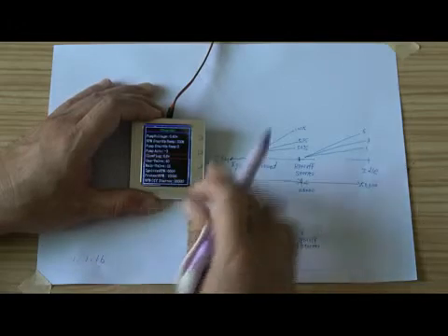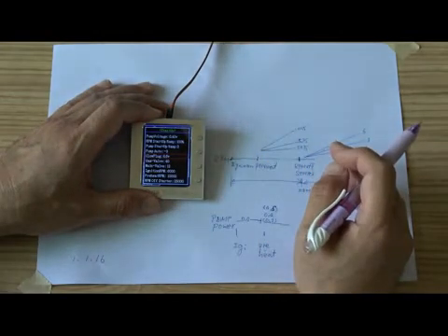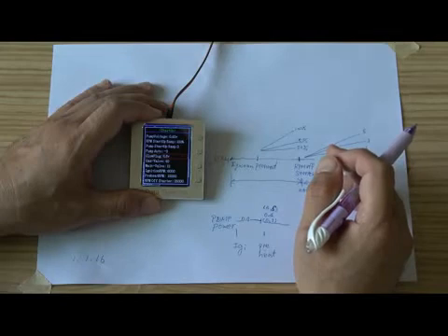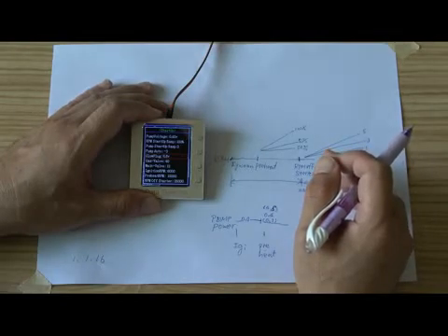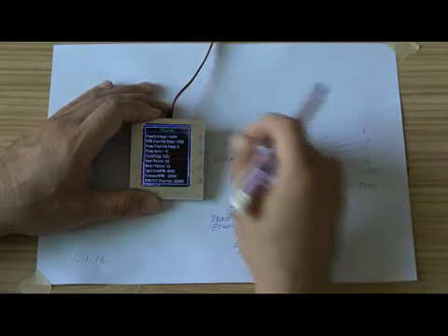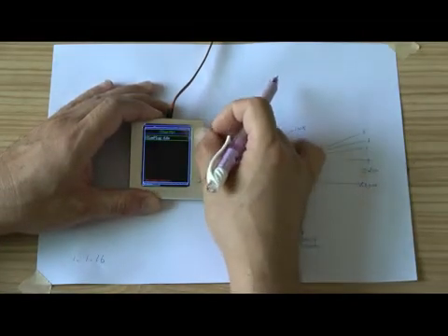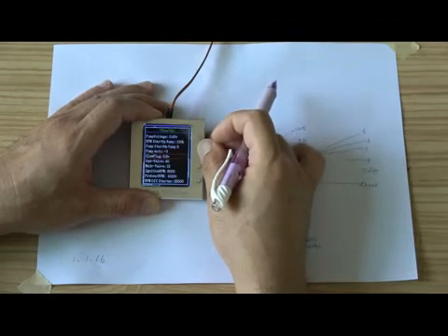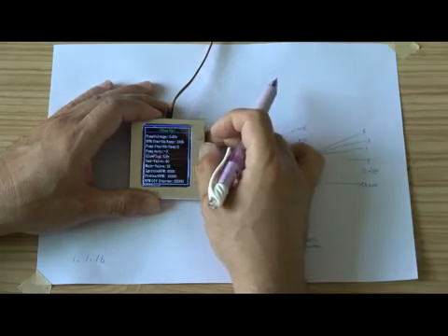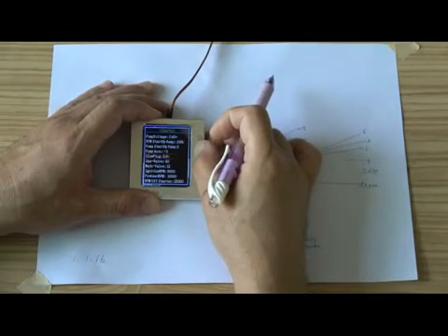If we use it a long time, and you find the ignition very slow and not easy to burn the fuel, you can increase it to 6.8. It controls the glow plug heater.